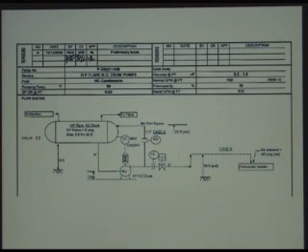So if we wanted to raise the NPSH from 6.5, then what we would end up doing is we'd either try to increase this from 10 foot to something higher. And on small tanks and drums, small vessels, you can do that, and you can do it without too much cost. But if you've got a 300-foot tall tower, you really aren't going to move that up 10 or 15 feet. So there are some physical limitations, but that's the most direct way of increasing the NPSH available to the pump.